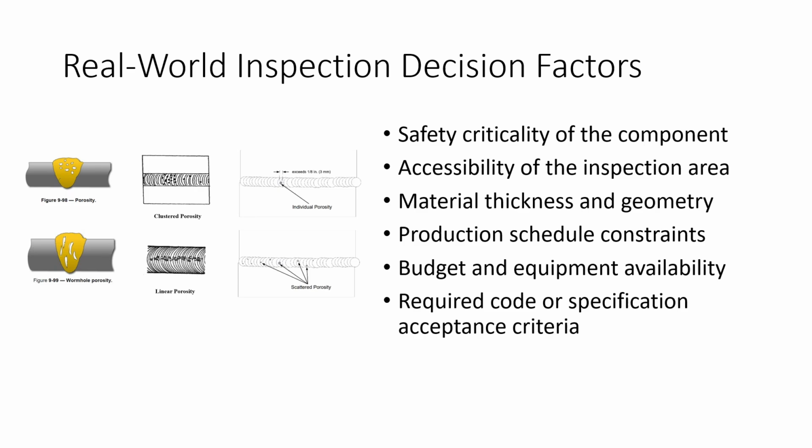But if we've got some kind of lifting lug, lifting eye, pad eye, weld, that if that weld breaks or fails, you're going to drop a component and it's going to punch a hole through the ship, some kind of spooling ship or oil tool, whatever they do out there in the Gulf. If you're going to drop something and it's going to sink a ship or kill people, you probably want to go that extra mile.